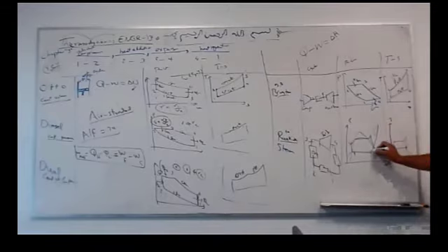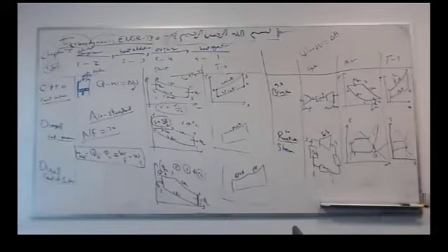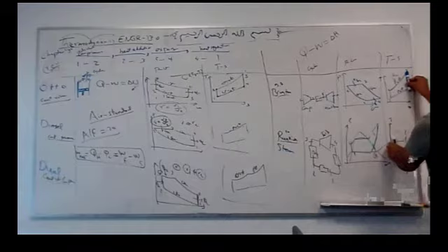Okay? The entropy increases. Actually decreases. It may be like this, something like that, because entropy may remain the same. This is a constant entropy line in the PV diagram, but this is a constant entropy line in the TS diagram. I like the TS diagram more for these cases, because isentropic processes are just vertical lines.